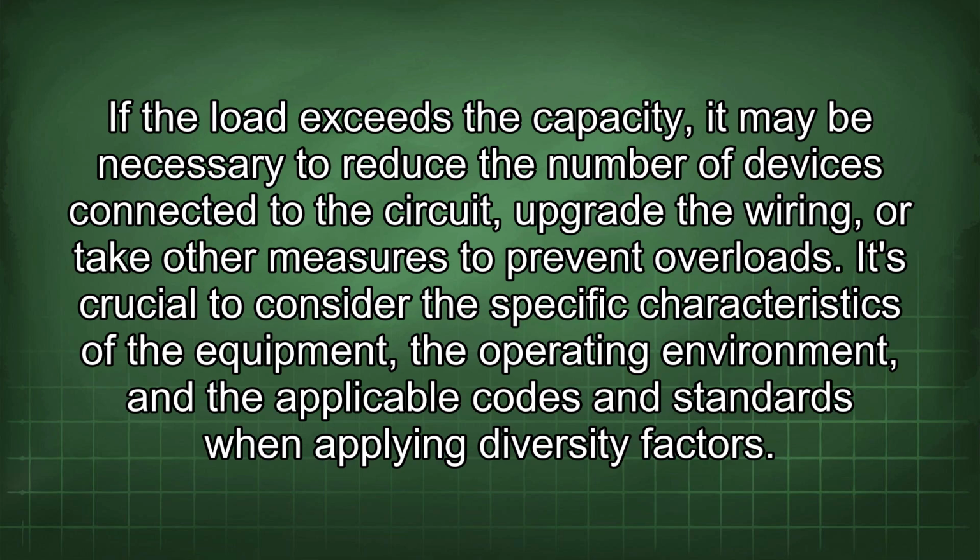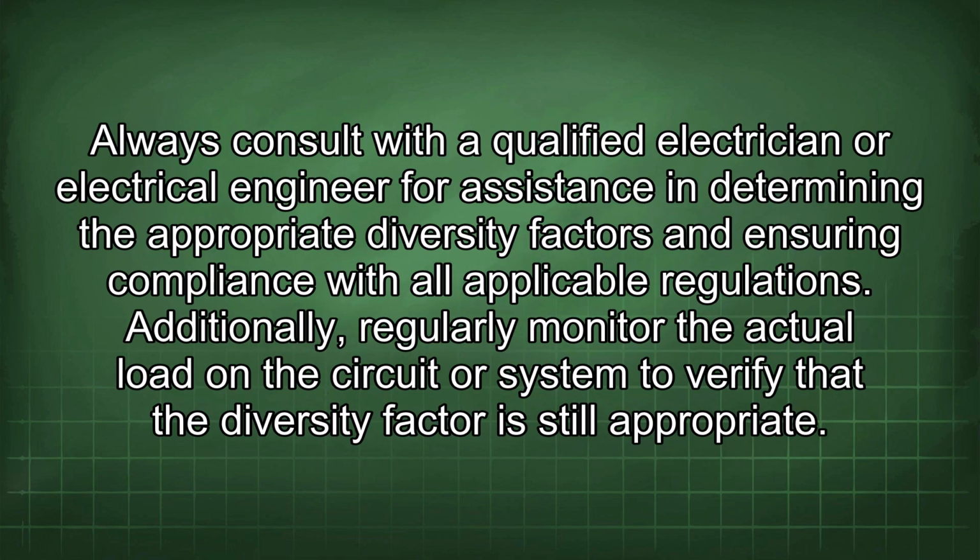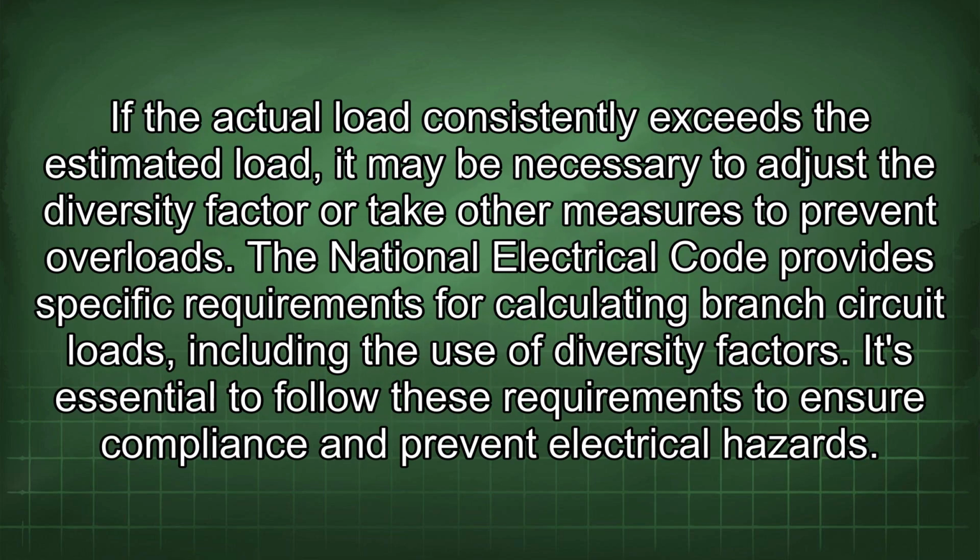It's crucial to consider the specific characteristics of the equipment, the operating environment, and the applicable codes and standards when applying diversity factors. Always consult with a qualified electrician or electrical engineer for assistance in determining the appropriate diversity factors and ensuring compliance with all applicable regulations. Additionally, regularly monitor the actual load in the circuit or system to verify that the diversity factor is still appropriate. If the actual load consistently exceeds the estimated load, it may be necessary to adjust the diversity factor or take other measures to prevent overloads.